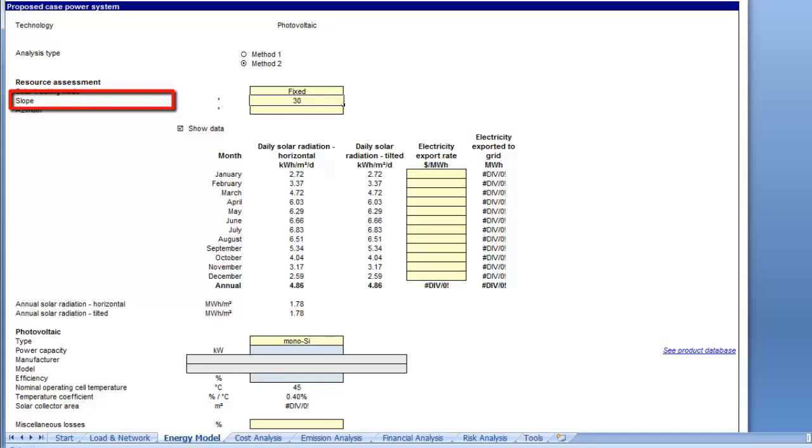Because this is a unique residential project aiming to generate the most energy and revenues possible year-round, for a fixed system, we will select a slope that is equal to the absolute value of the latitude at the project site. Several RETScreen simulations indicate that 30 degrees will result in a higher energy production. This is also close to our latitude value, so we will use it as our slope.